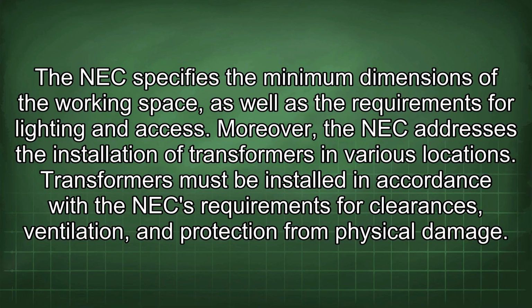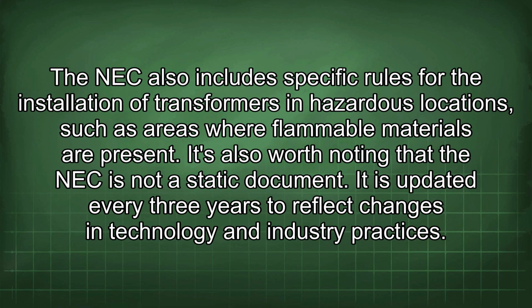Moreover, the NEC addresses the installation of transformers in various locations. Transformers must be installed in accordance with the NEC requirements for clearances, ventilation, and protection from physical damage. The NEC also includes specific rules for the installation of transformers in hazardous locations, such as areas where flammable materials are present. It's also worth noting that the NEC is not a static document.